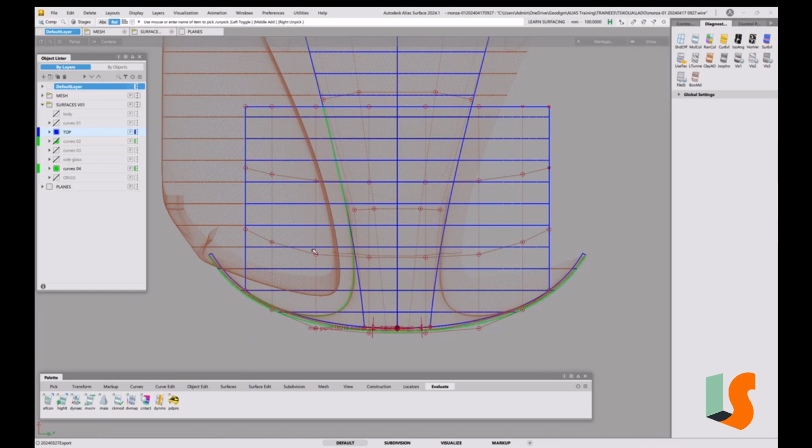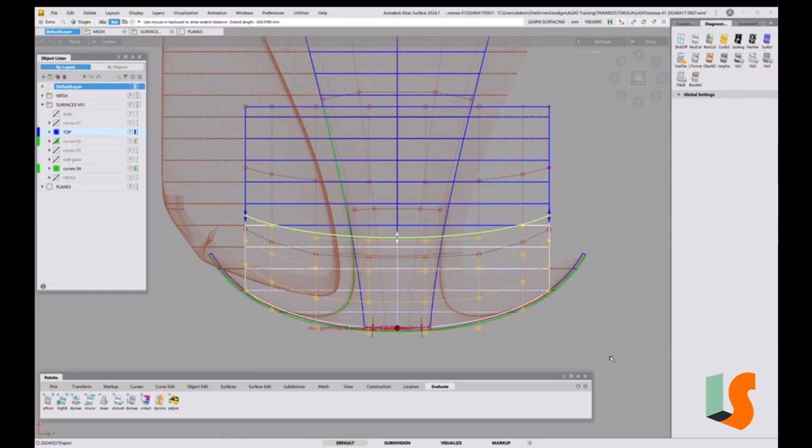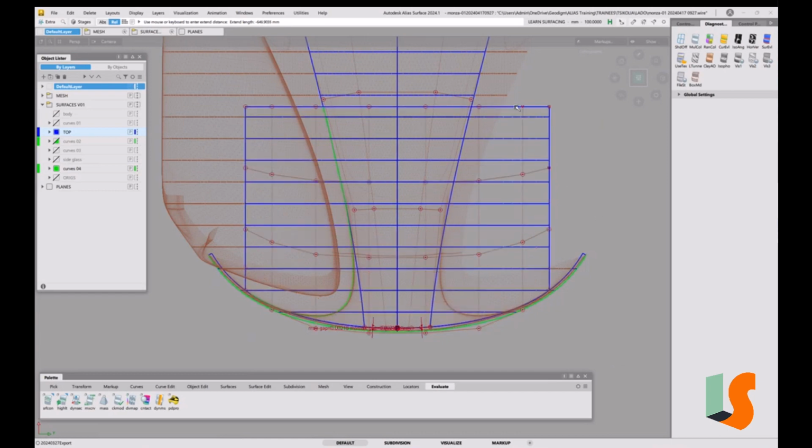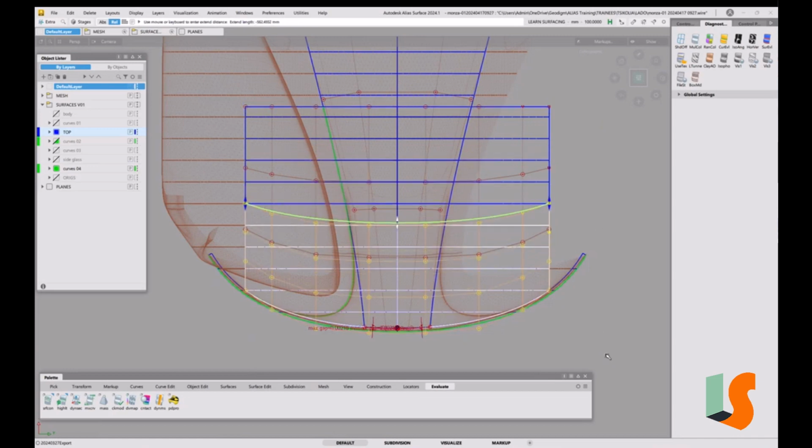Because the trouble is, the next step I'm going to do is quite a big step, because I'm thinking of just putting a straight line across there. Although, let's see what happens if I extend this. So remember, this is a copy, so I can do whatever I like with it because I've got the originals back there. I'm just wondering whether it might be better to just extend it, because if I do that, I'm extending it backwards, which is the same as trim or detaching rather. It's the same effect, but what it means is that surface is 100% the same as the original in terms of its shape. I think I'll be better off doing that.